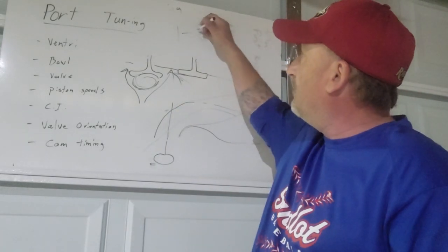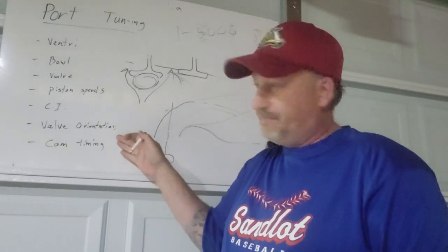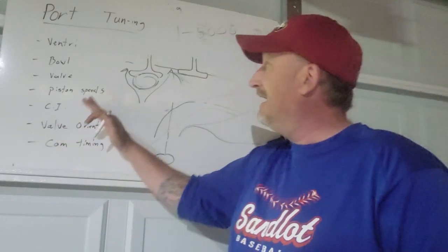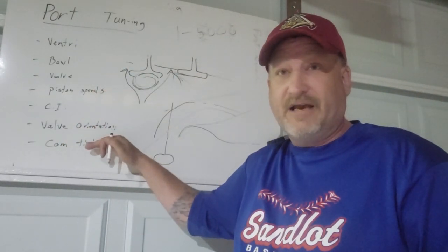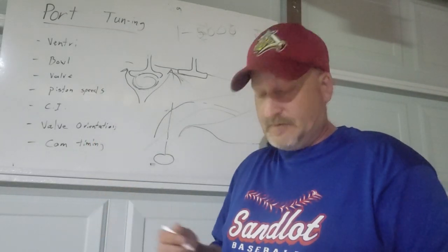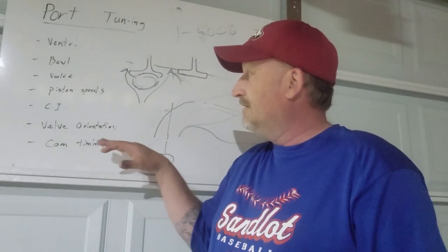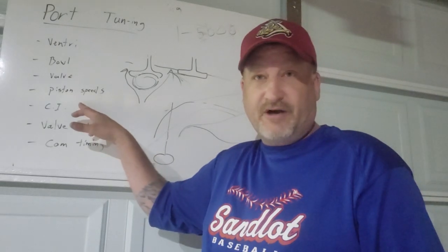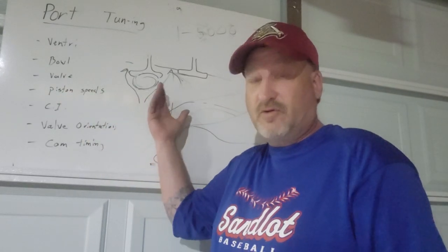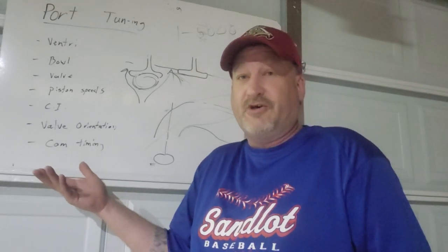engines that operated in that 1,000 to 5,000 RPM range. So by altering any one of these mechanisms or components, you have to redesign all of the rest of them to also work together in your specific RPM band. So if you're going to modify your cubic inch with a stroker engine, you also have to realize you need to modify the cylinder heads and the intakes, or even the carburation and the cam timing, to take advantage of that additional vacuum that will be created by the larger cubic inch.